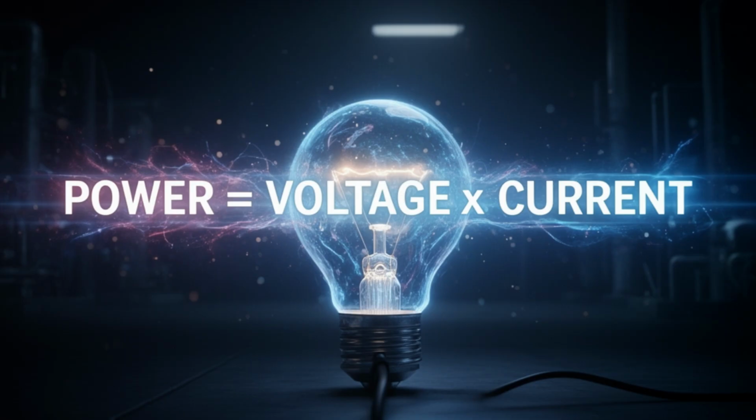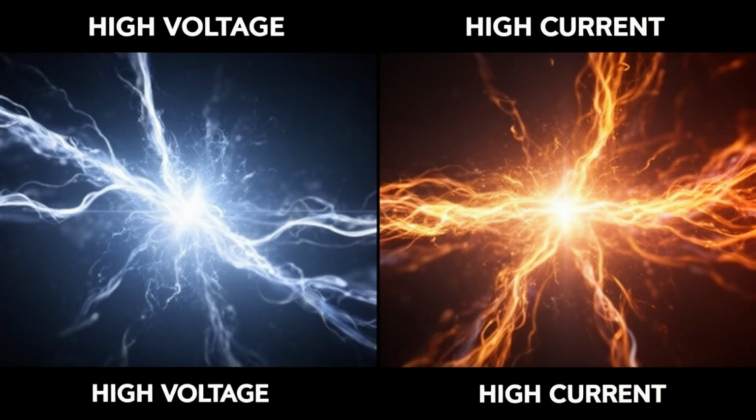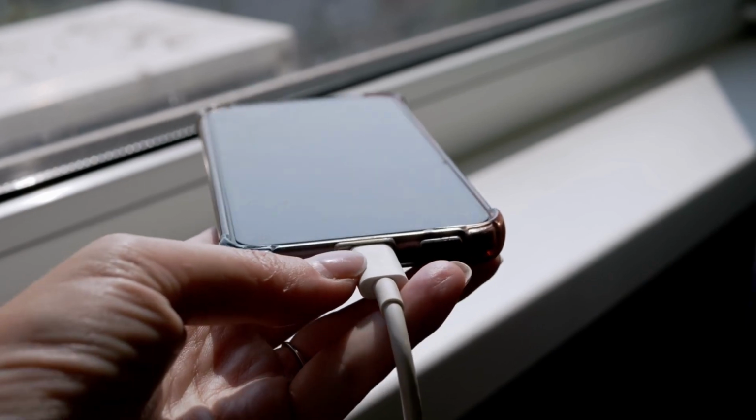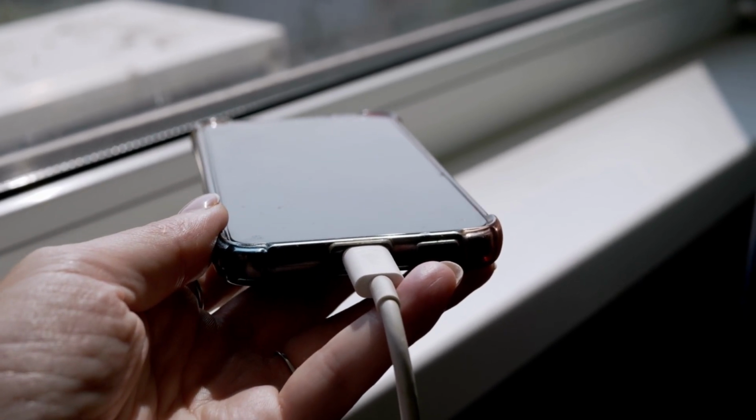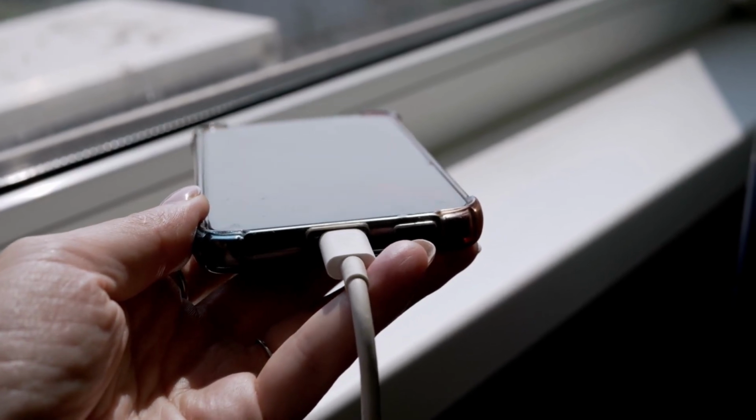All of this comes back to power, which is simply the rate at which electrical energy is used, measured in watts, where power is the product of voltage and current, meaning higher voltage or higher current results in more energy being consumed per second. This explains why high-power devices like heaters, ovens, and air conditioners draw more current and require thicker wiring, while low-power devices like LED bulbs and phone chargers operate efficiently with much less energy.